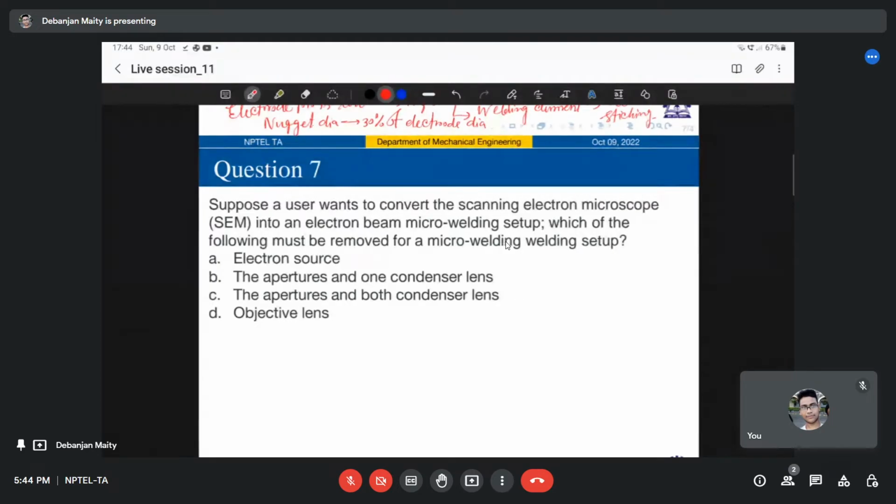What can be a further advantage? A further advantage is controllable heat transfer. So in droplet welding, there will be a controllable heat transfer given only by the heat content of a single drop that is sufficient to produce a high temperature weld.